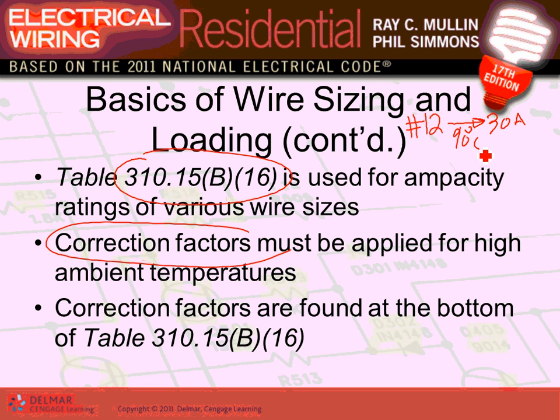Okay, so we derate. So when we derate, we cut it. Say we derate it by 0.5, then the ampacity of number 12 becomes 15 amps. And we'll talk about the rating. Darren, I don't think you guys did the rating, right? You did a little bit, yeah. We'll talk about the rating. We'll do some examples about the rating too, how to derate for the ampacity. Now that's the rating based on temperature.